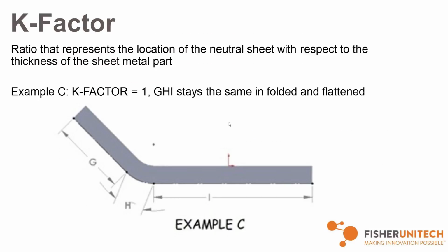But Jeff, did you have any input on any of that? Once the K factors are defined, like you said, you want to keep them. Block is a great resource for that already. They have developed and given us a chart, and for the common gauges that we bend, we already have those limits set. You rarely have to change them no matter what material you're using, whether stainless, aluminum, or even mild steel.